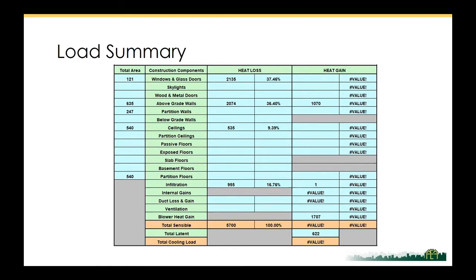And I mean, right now we're assuming 0.55 U factor, and Title 24 is 0.32. I've seen U factors as low as 0.25. So that's really not too far-fetched to increase the windows, and that may be a recommendation. Increase the efficiency of the windows. That may be a recommendation that we make to this property.